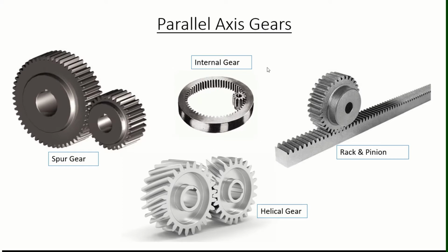The internal gears have teeth cut on the inside of the cylinder or cones, and are paired with the external gears like this. So the main use of internal gears is for the planetary gear drives and the gear type shaft couplings. There are limitations, however, in the number of teeth differences between the internal and the external gears because of the involute interference.